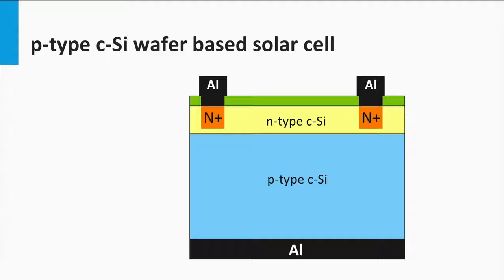At the back surface of the solar cell, we have similar issues playing a role. As the electrons are collected in the N-type layer, the holes are collected at the back contact. As electrons are the only charge carriers that exist in a metal, you have to realize that the holes recombine with the electrons at the contact interface. If the distance between the PN interface and the back contact is smaller than the typical diffusion length of the minority electrons, these minority electrons can be lost at the defects at the back contact interface due to Shockley-Read-Hall recombination. How can we reduce this loss mechanism?